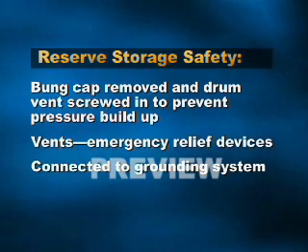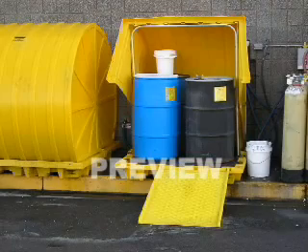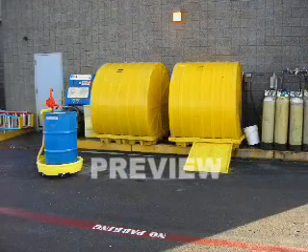Drums also should be connected to a grounding system. This eliminates static electrical buildup when dispensing from the drum. If your plant does not have a drum storage room, drums should be stored in a safety cabinet. They are available in sizes to hold drums vertically and horizontally.